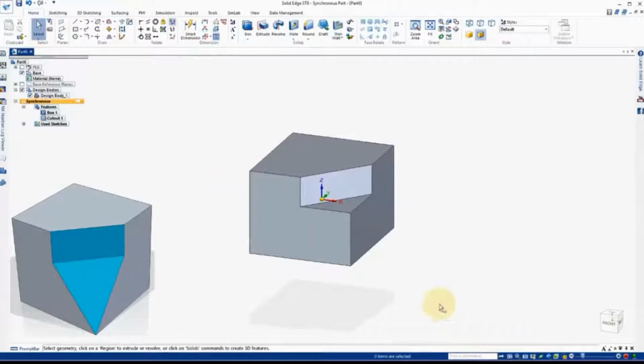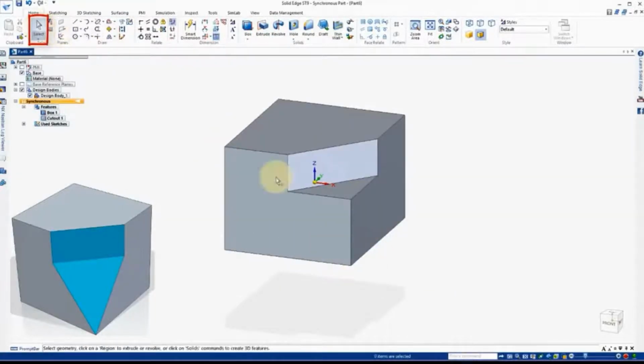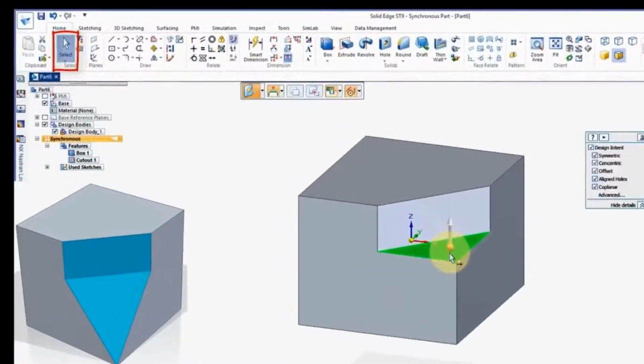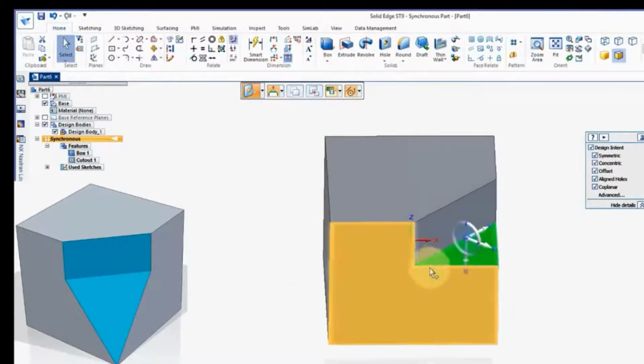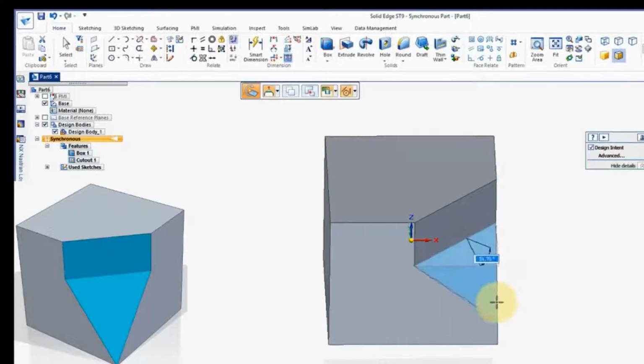Because what happens when you have the magic wheel, all you do is just go and touch on this face, and we come in here and we pull the ball over. If you're having trouble seeing that, just rotate it around. Then you grab the magic wheel and just spin it around and drop it down.